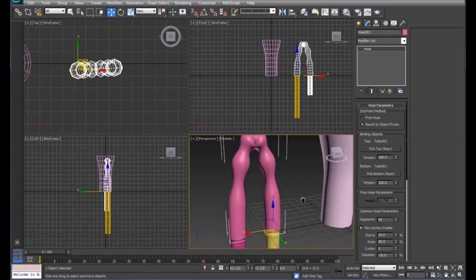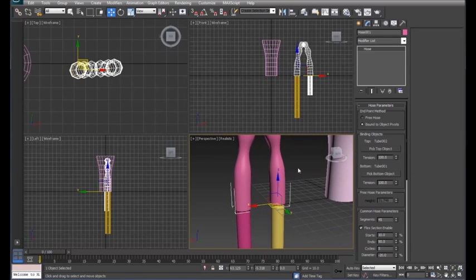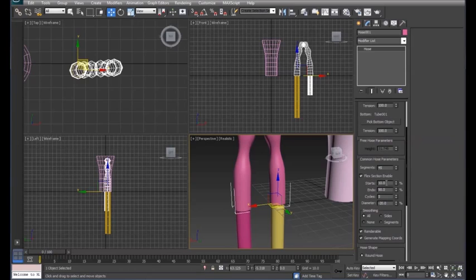Alright, so now we have a little bit of editing to do with our straw. So the first thing we want to do is come down and set the starts to 0 and ends to 100 because we want it to start at 0 and end with 100%, and we'll look at what that does in just a little while. On our cycles, we're going to put our cycles up. That's going to tell us how many bumps are in there. If you get it too much, it'll actually start going the opposite way, so we'll leave it at that for right now.